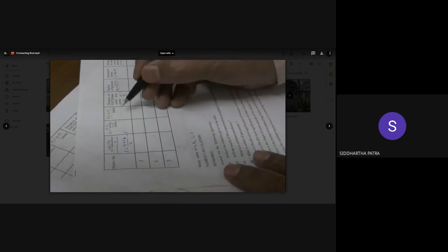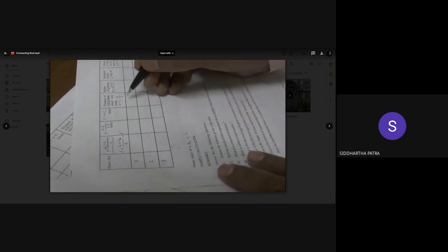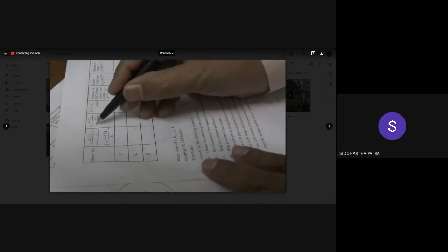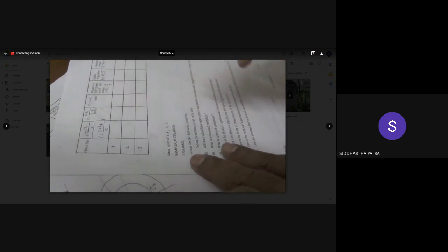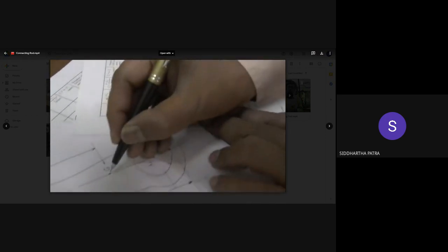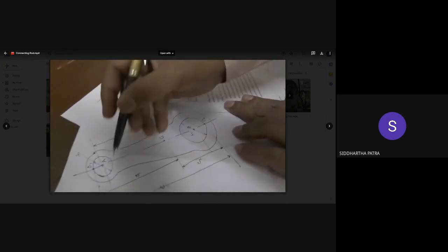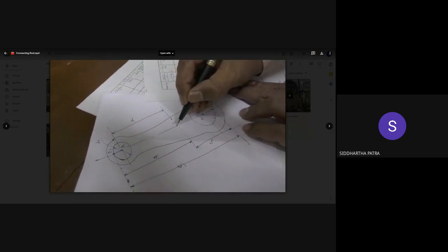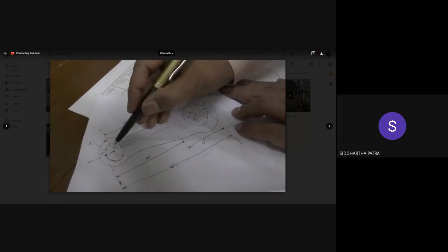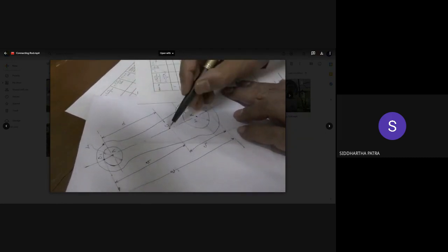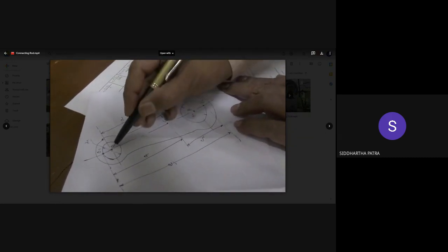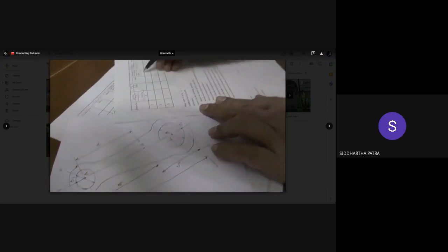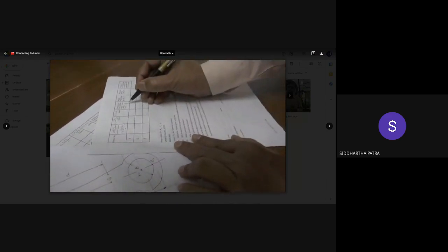Now you have got these relations and the values of C1 and C2. So once you find out C1 and C2, you have located the position of the center of mass. Then what is important is from the small end center to the center of mass, and that is C1 minus D1 by 2.